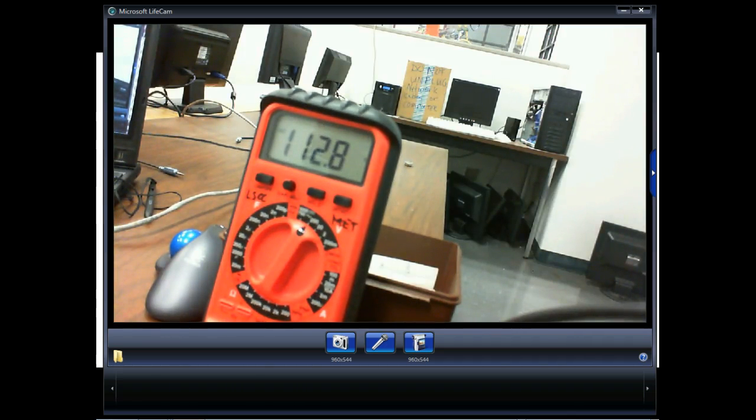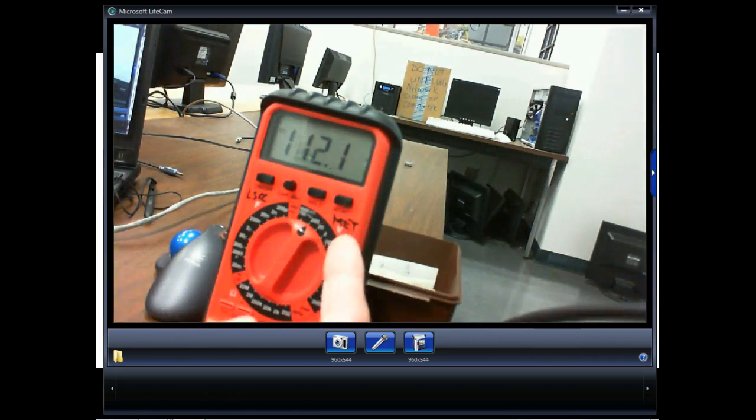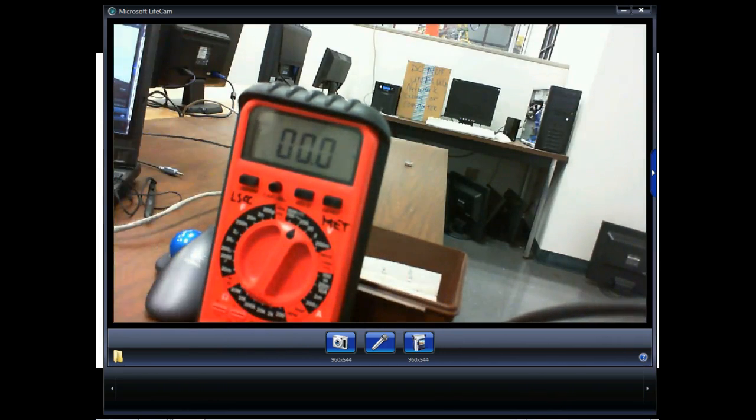Yes. So this is very important on your meter, especially a meter like this, because all it does is take a little button right there, and now it measures 0, and I don't look up here and see this DC up there, and I think there's no voltage in the circuit, and I stick my hands in there and I get my butt shocked, right? You understand that?